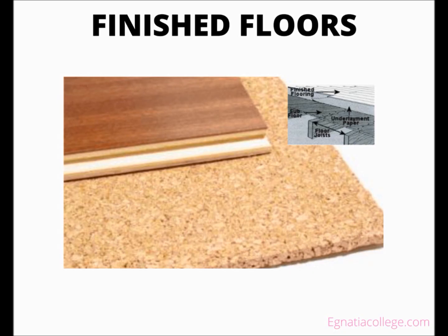Architectural drafters differ in how they indicate what underlayment is to be used and how the finished floor is to be installed. Some do not include any underlayment on the drawings, but rely on the builder's knowledge of good construction practices. This is a dangerous practice. If you find this situation, the architect should be asked for clarification.